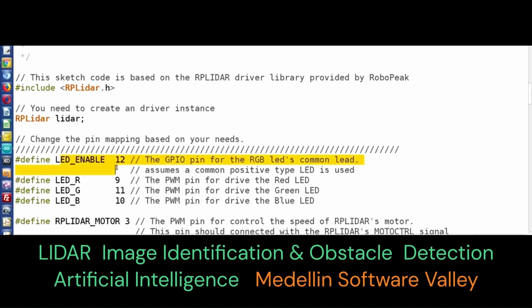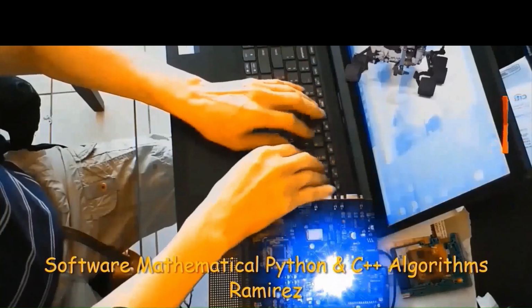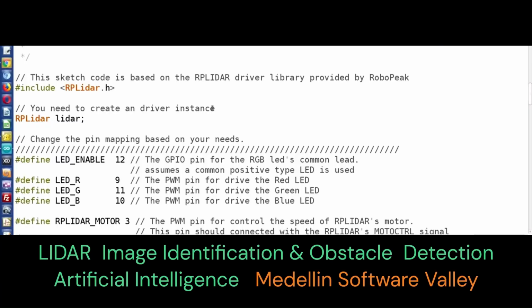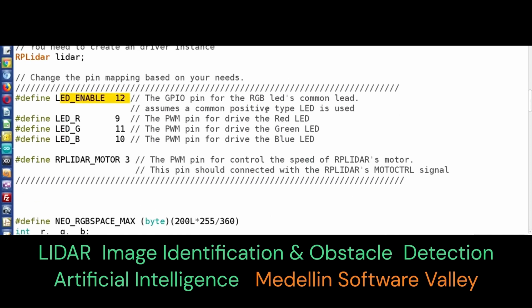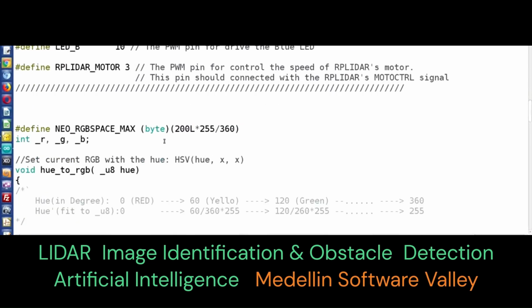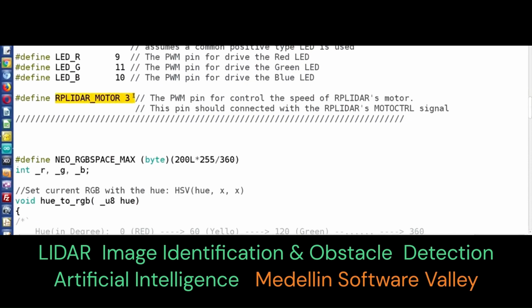The mode pin is inserted which places the sensor in analog input or analog output mode, and as a result, each distance corresponds to an analog output value that must be sampled by the analog to digital converter, the ADC, at the host side, at the CPU side. And then it will take the data using the I2C protocol.